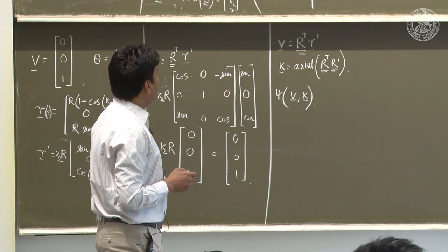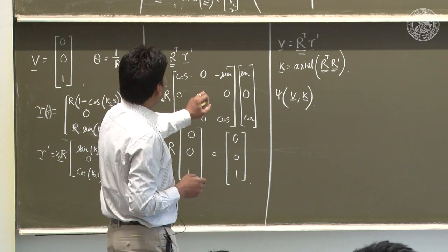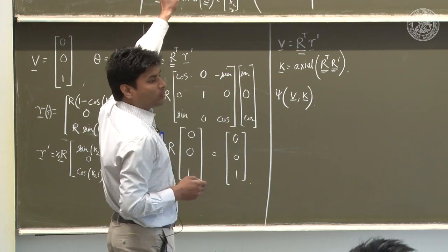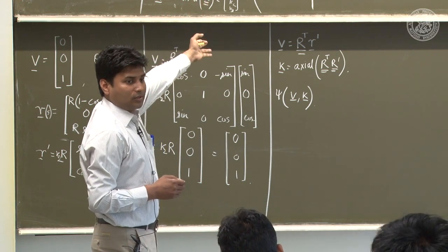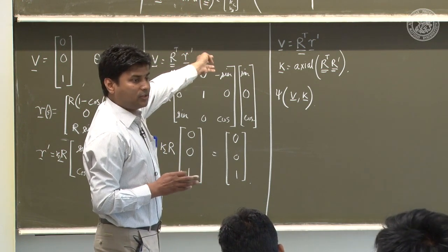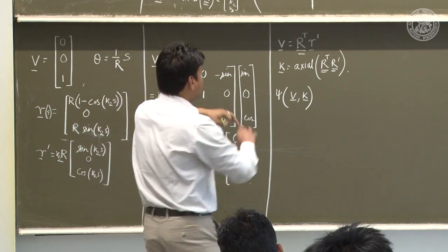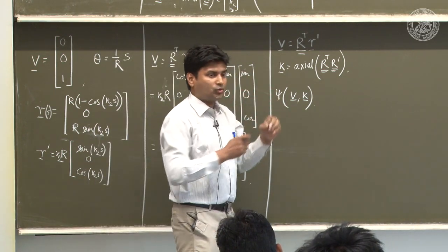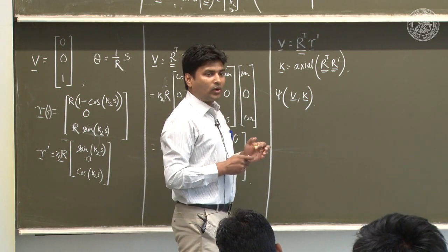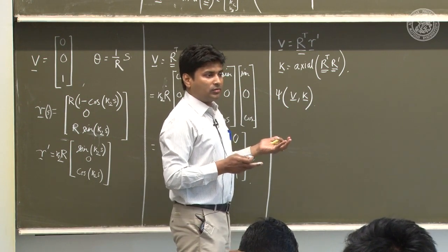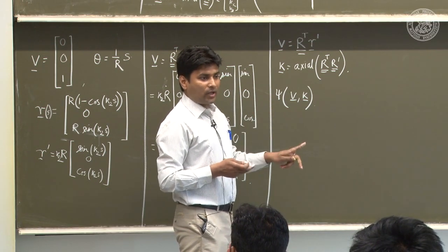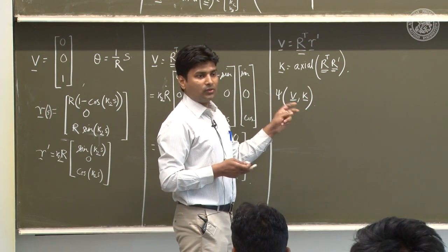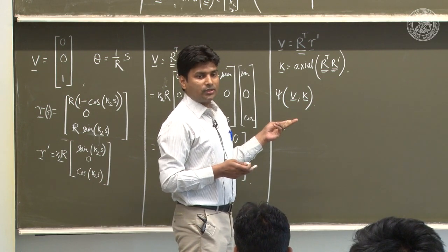Okay, our goal was to relate the forces and moments that we see over there with the kinematic quantities. We still haven't achieved that. We just got some idea about the psi. How should the psi look? What all should it depend on? We found there are 6 quantities: 2 shears, 1 axial stretch, 2 bending curvatures, and 1 twist. Total 6 strain measures.